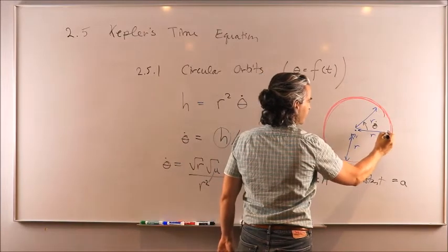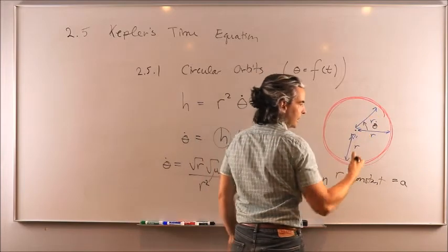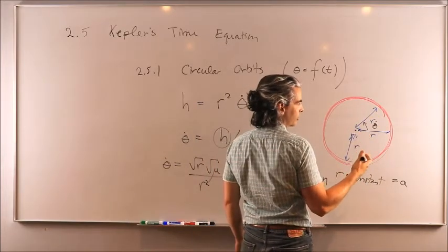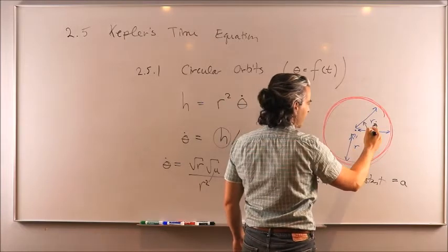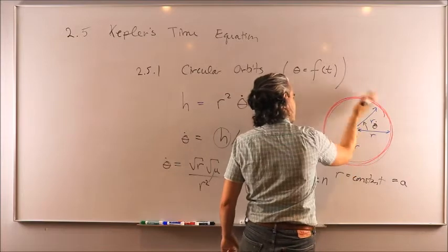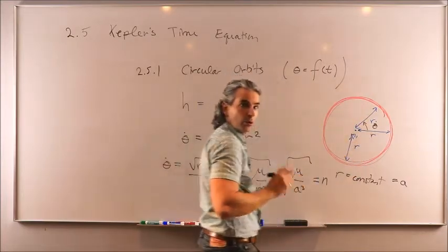Okay? Or in other words, the position vector r, because yes, there is an acceleration by virtue of the two-body equation of motion, minus mu over r cubed times the r vector. But what I mean is that the position vector, in terms of its angular motion, does not accelerate or decelerate as it does for an elliptical orbit.